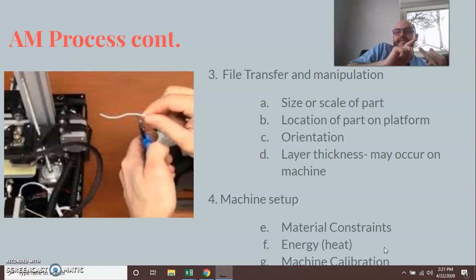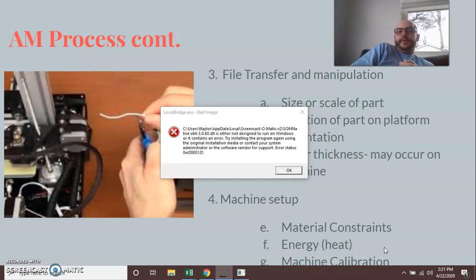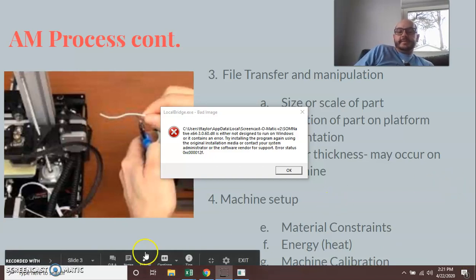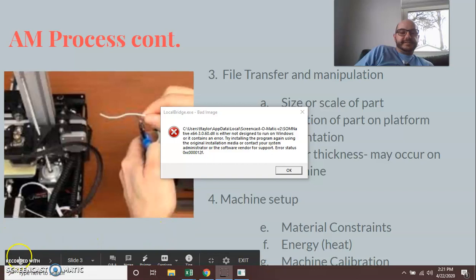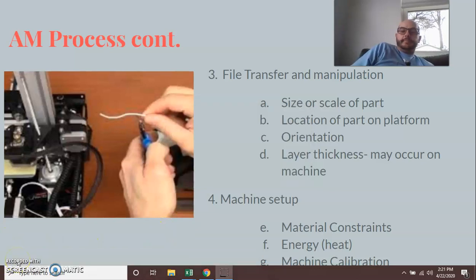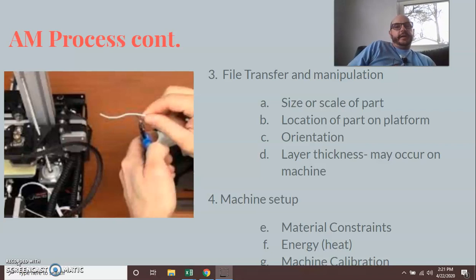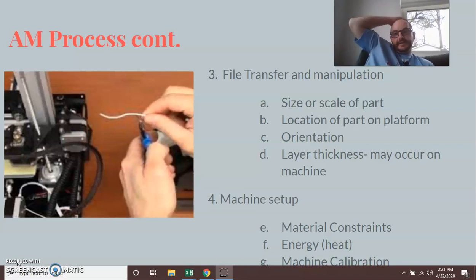The Stratus and the Artemis both use heat and melt the parts together. So we make sure our machine is up to the right temperature, because our Stratus has an oven, so it basically bakes the material, whereas the Artemis has a heated plate that is used.